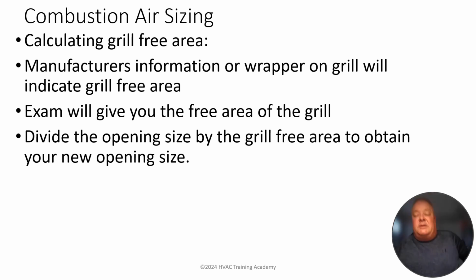One of the things I also want to talk about: a lot of times you put a hole in somebody's wall, depending on where that hole is. Maybe it's into a nice finished rec room that they entertain in, or a nice area where the family gathers, and they don't want this ugly hole protruding. So a lot of times we'll put a grill over the hole just as a decorative piece. It still allows air to travel back and forth, but it looks more appealing than a hole sitting in the wall. A lot of times that grill is going to take away some of the area of air that can transmit back and forth from one room to the other.